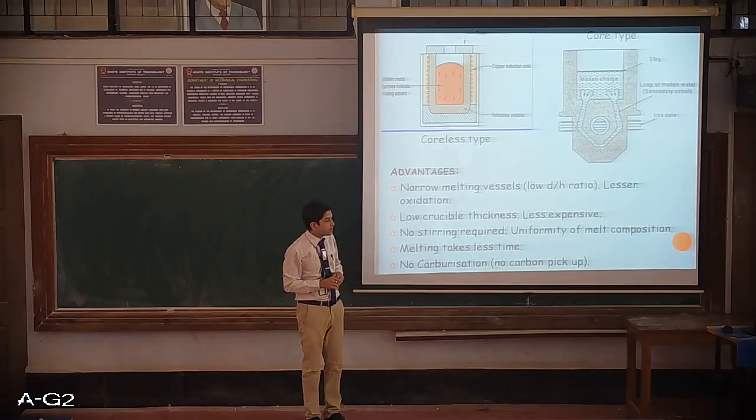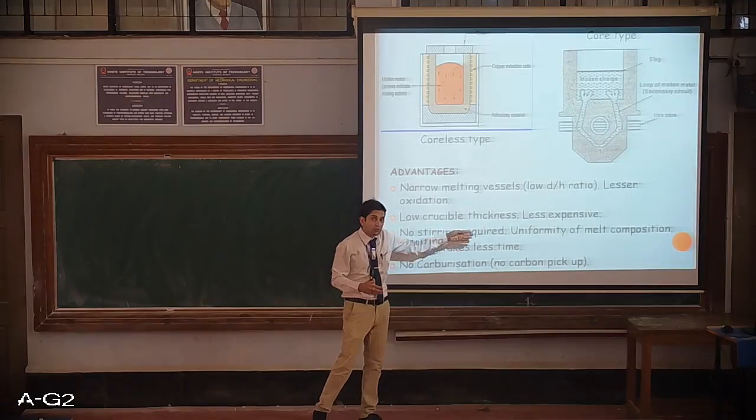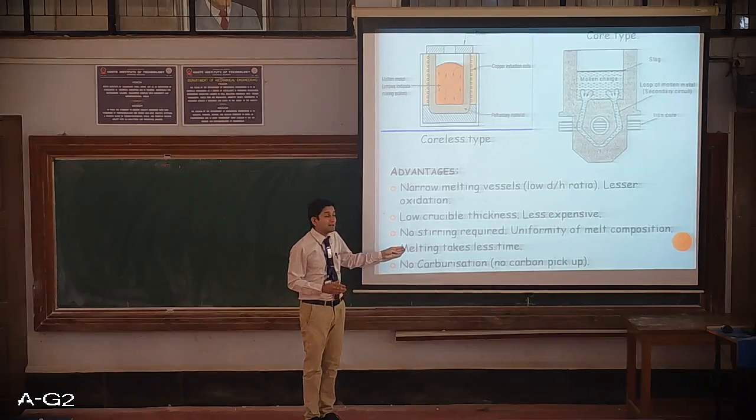No stirring is required. It will occur by itself. That's an advantage of this one. I have discussed it earlier also. Uniformity of melt composition. Since stirring takes place by itself, uniformity of the melt composition happens. Melting takes very much less time. Within seconds the melt will occur.